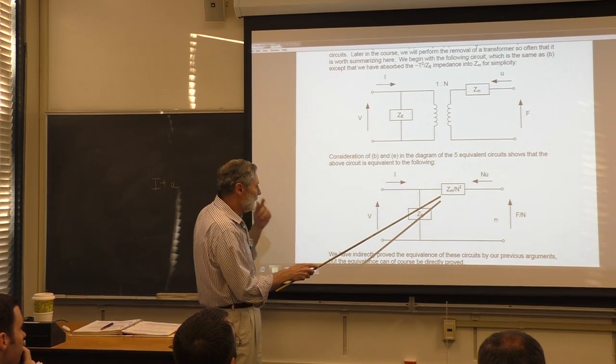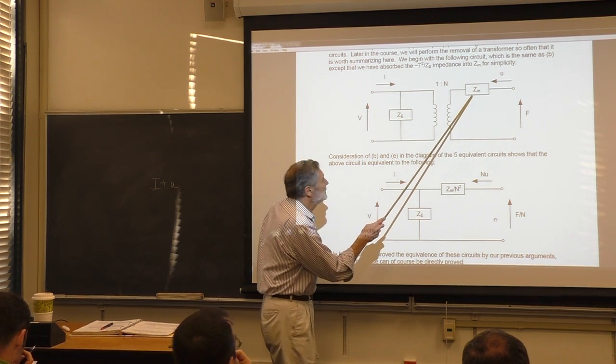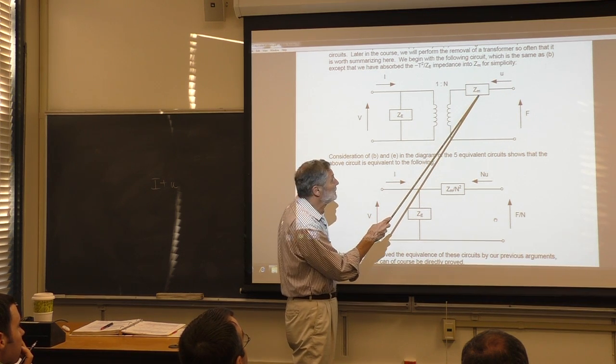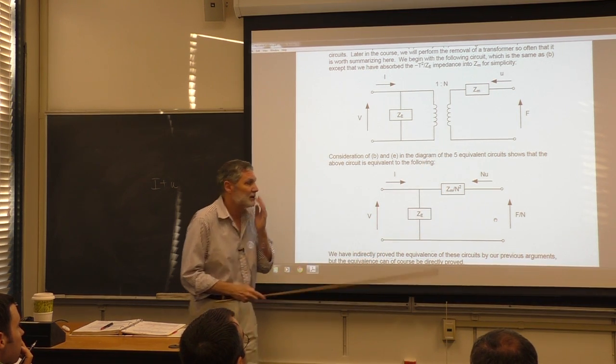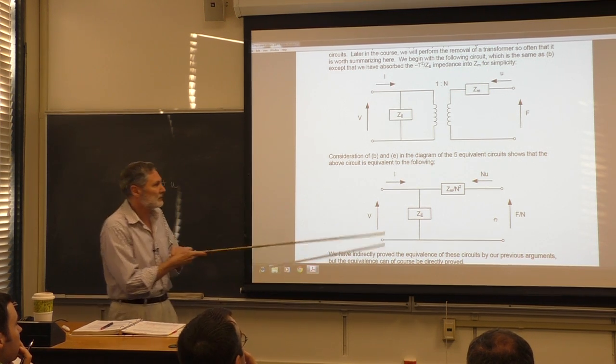This is the one that is a little bit harder, but believe it or not, you'll get used to it. It turns out that when you take this mechanical impedance, lowercase m, and divide by n squared, you get units of electrical impedance. So it's a fully electrical circuit here.